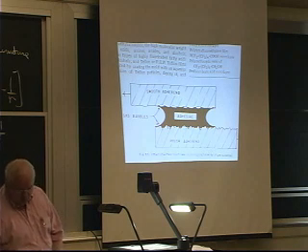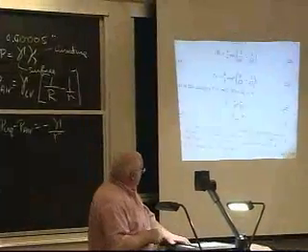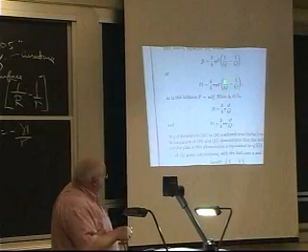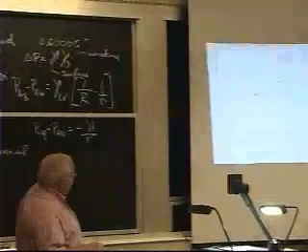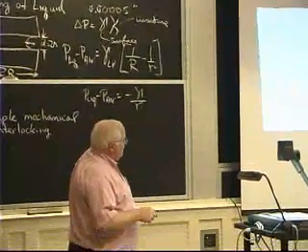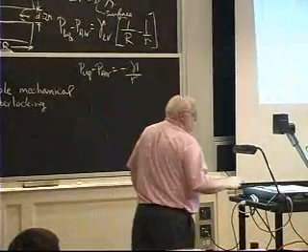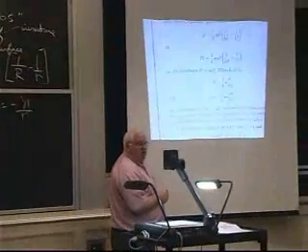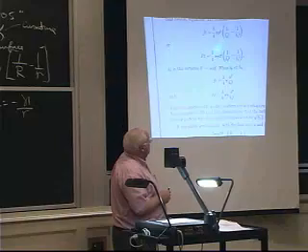Those are the two basic ways, but if I go back, 2 types of bonding, so those are my 2 themes today. But one of the things I also have here, I can make it thinner, and that goes as 1 over the thinness squared, okay? But the other thing in here that I can change is the viscosity. Now, some of you know some fluids. So if let's say I make a joint that's 10 times thinner, that'll make it 100 times stronger. And that turns out to be approximately correct.